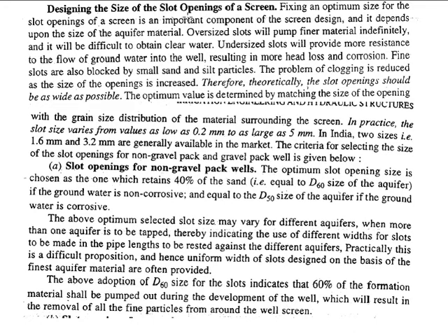If it is too small, it will restrict the entry of the water, and if it is too large, then apart from the water it will also permit the entry of fine particles and gravel, which we don't want. So therefore certain considerations must be taken into account when designing the size of the slot.